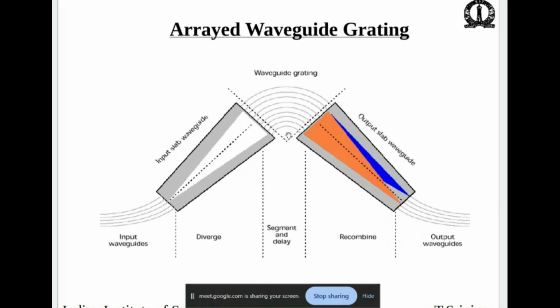These are called waveguides of different length. So there is a different phase shift in each of these. And then when they combine in this mixing portion, by the end of this mixing portion, the maximum will be only at that particular port. For example, blue is shown to be maximum here. Orange is shown to be maximum here. So these delay lines are dependent on the wavelength.